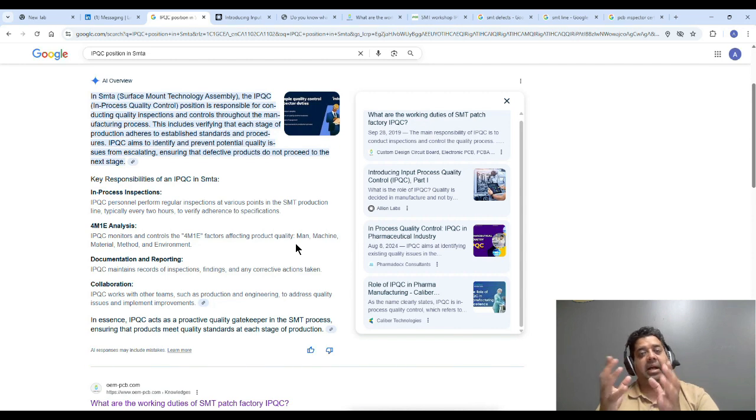And then the stencil, as I said, different thicknesses, different materials, and then even on top of the material, different companies make stencils with different coatings, special coatings on top. Again, those things need to be figured out, and you need to focus on all that as well. Method is all about process engineering.